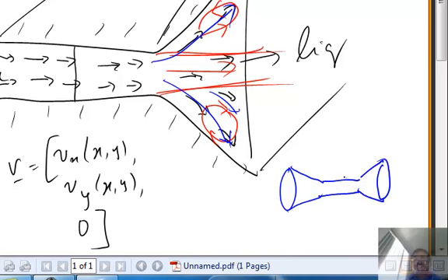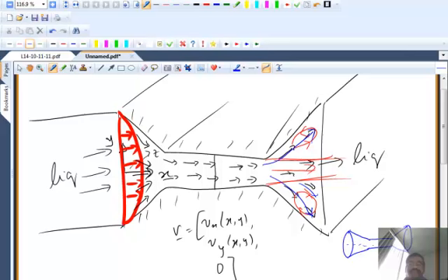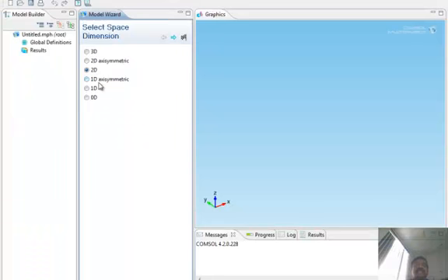So in an assignment, if I ask you to do this, a converging, diverging, but it's a tube, a circular cross section, then there will be an axisymmetric condition. So you would select 2D axisymmetric, which basically means Comsol will solve in cylindrical coordinates. And similarly, you have 1D axisymmetric, but in 3D, it's general. There is no symmetry condition imposed.